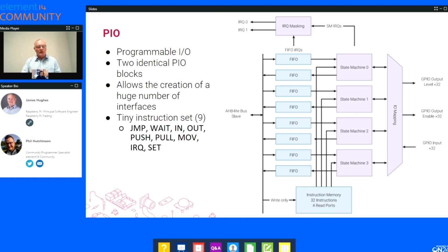One state machine handles frame and scanline timing. One generates a pixel clock, and another one generates the pixel data and unpacking run length scanlines. It's really quite something to see that this tiny little core, with the addition of these PIOs, doing things like DPI.